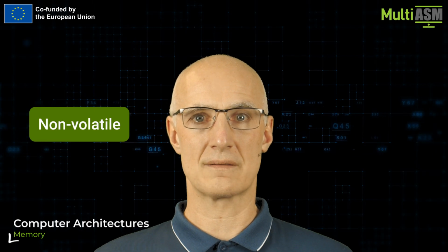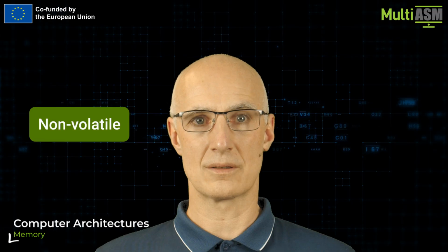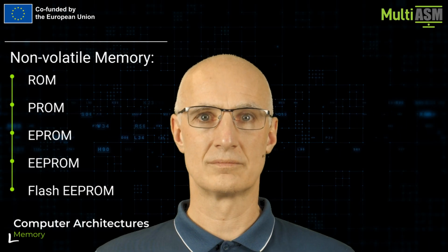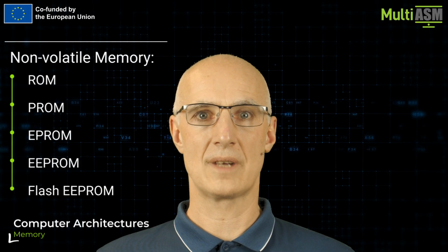Non-volatile memories are used to store data that should be preserved when the power is off, such as program code, constant data tables, and computer parameters, for example, network credentials. The hard disk drive or solid-state drive is also a non-volatile memory, although not directly accessible by the processor via address and data buses. Non-volatile memories are implemented as ROM, PROM, EPROM, EEPROM, Flash EEPROM, and FRAM.